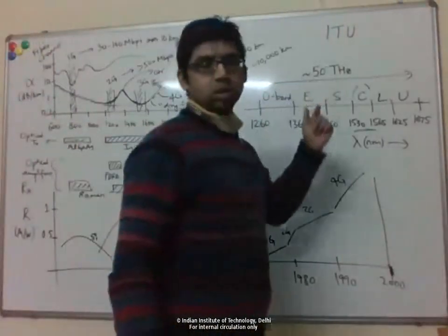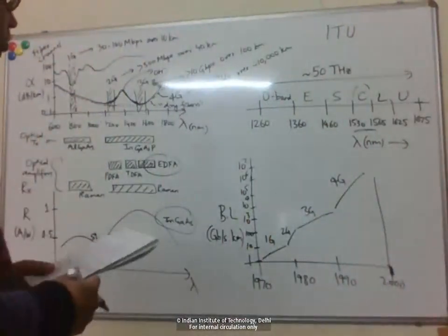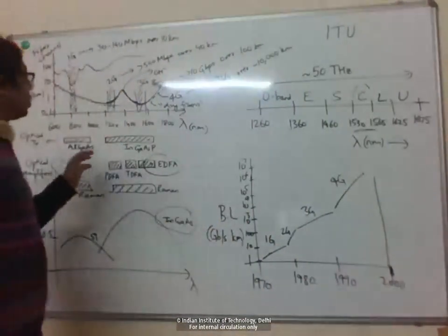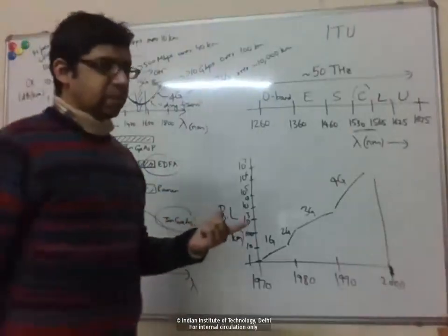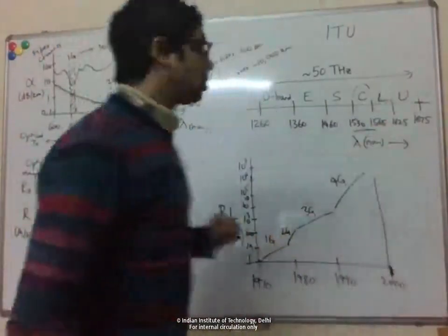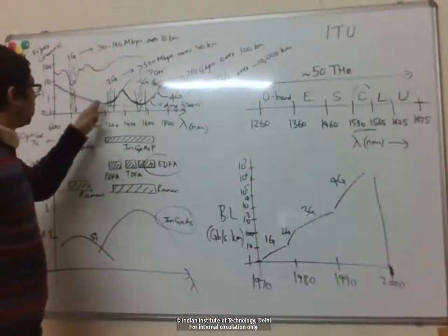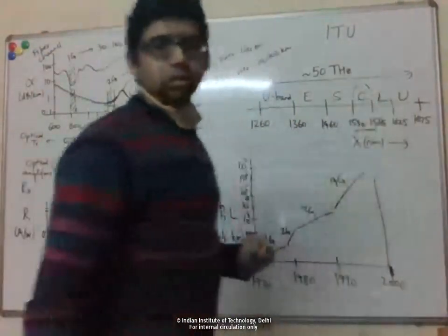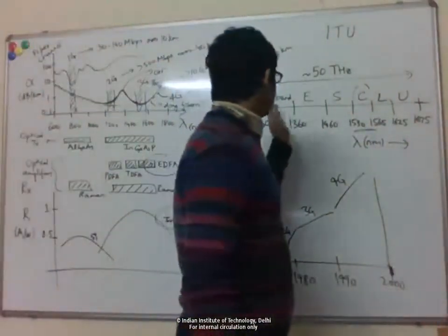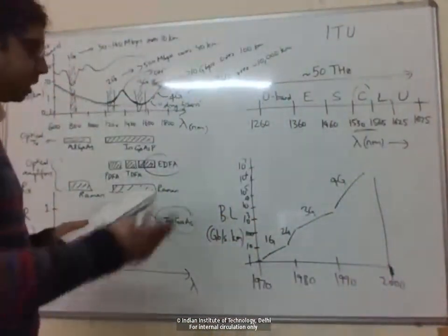Okay, so this bandwidth is really huge. Like no other channel actually compares, right? So again, going back to our discussion from the last time, right? We want to define a channel bandwidth where the properties of the channel don't vary too much over the entire band, right? So here, for example, with these dry fibers, the loss is sort of flat over this entire range. Okay. Of course, some other properties like, for example, dispersion, etc., will vary with wavelength, but there are ways to again compensate for that. We discussed.